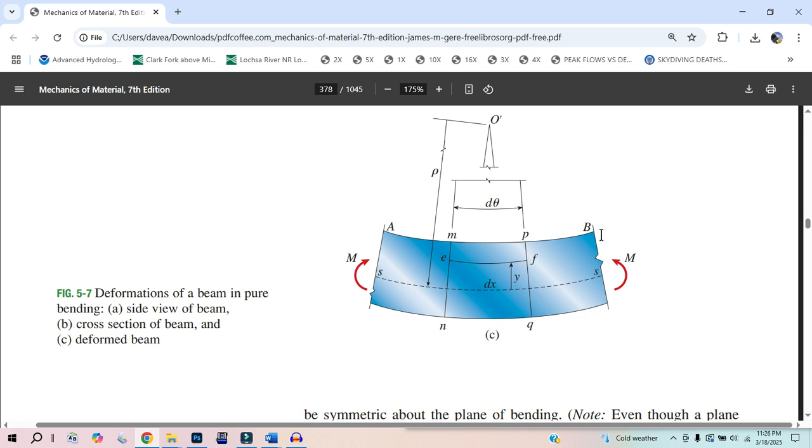I think that's a pretty good idea: every time you see a moment, put the force on the paper. In this case, what we're going to find is a heavy duty force up here, really compressing this line. In the middle, we're not going to have any force. And down here, we're going to have forces that are really stretching it out. Let's go up halfway: we're going to have half the force crunching this direction, twice as much as the force up here, and zero in the middle.